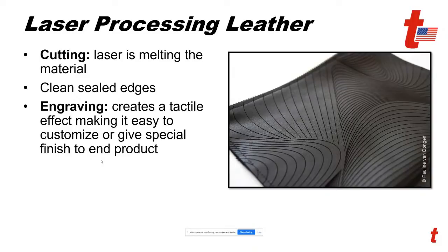Processing leather is pretty easy with lasers. When cutting it, the laser melts the material, especially your synthetic leathers, and your synthetic leathers produce clean, sealed edges. Engraving it creates a tactile effect. It makes it easy to customize or produce a beautiful finished product.